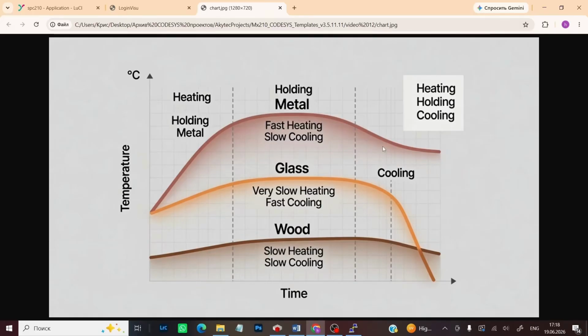When cooling, the surface of the instrument tries to contract, so the center of the material contracts and the surface stretches, since the surface cools faster than its hot center, which is trying to expand. And the thicker the material, the greater these stresses become. That is, they become more dangerous in both phases. For example, metal and glass are harder to break under compression than under tension, while wood, on the contrary, is easier to break under compression than under tension.